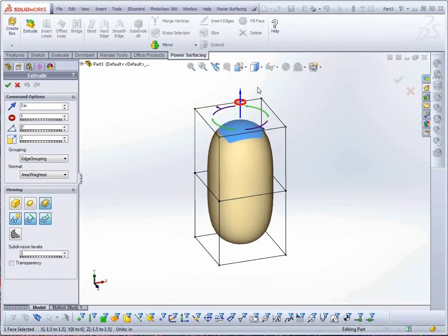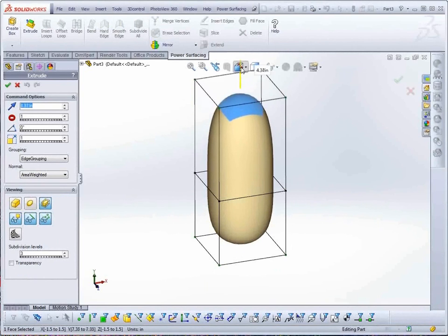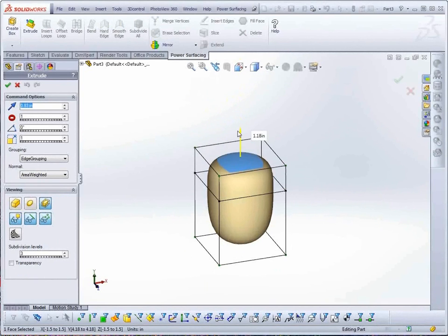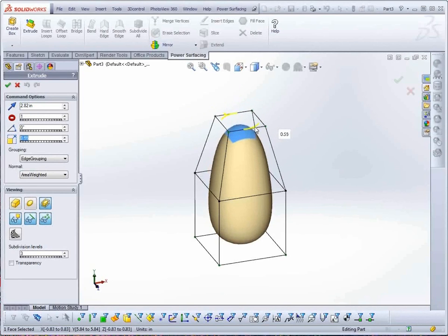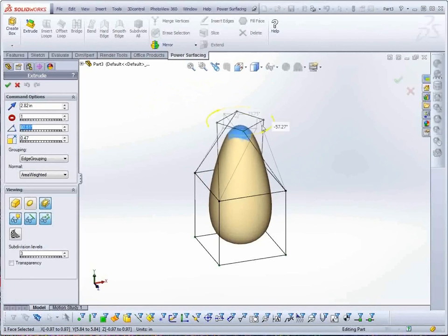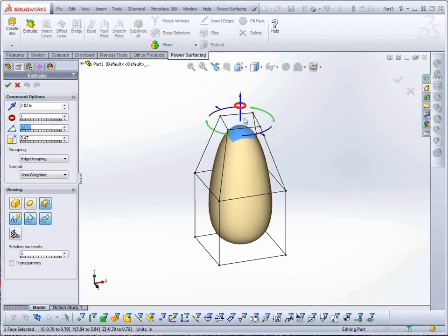With Extrude, you can adjust the extrude distance with the Distance gizmo, scale the extruded face with the purple Expand gizmo, and rotate the face with the green Rotation Angle gizmo. You can also increase the number of segments with the red Increment gizmo. To use it, click and drag up and down in the viewport, regardless of its orientation.